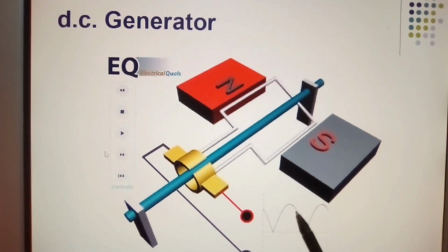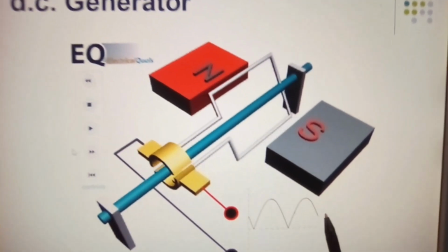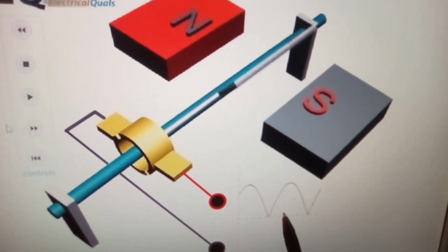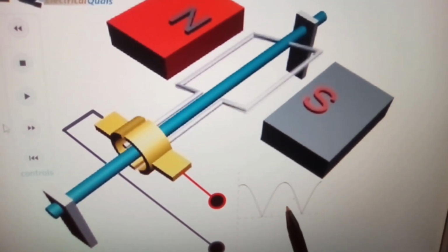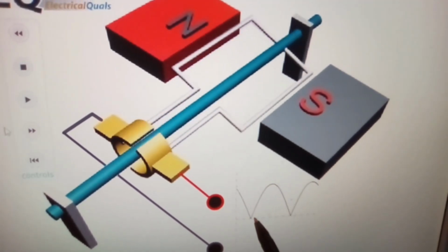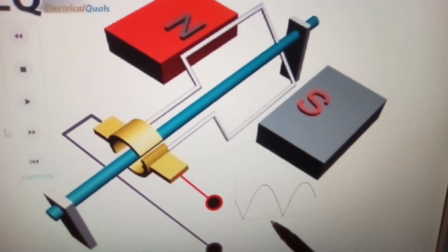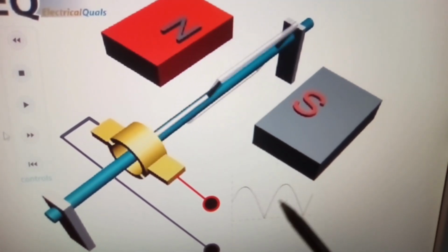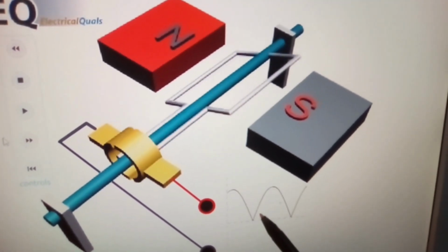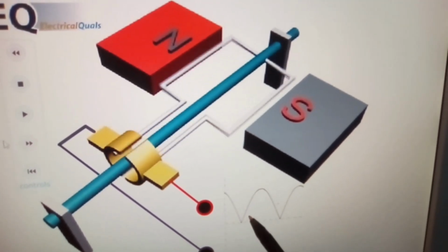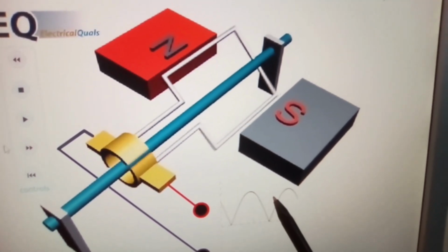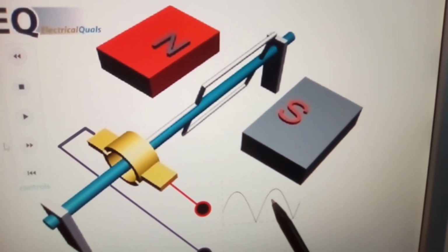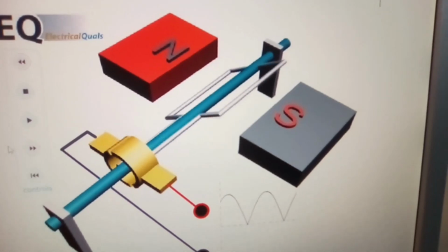Now this waveform here, can you see it? This waveform here is a half waveform. It's not rectified, it's a half waveform. It's simply converting the negative half cycle of the AC waveform into a positive half cycle. So you have a number of cycles here. Now to get this smooth and continuous, you will need to apply a capacitor in the circuit, which will give you a smoothing effect and a more consistent DC output.